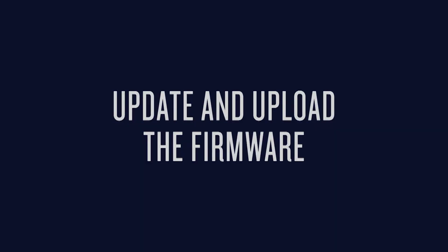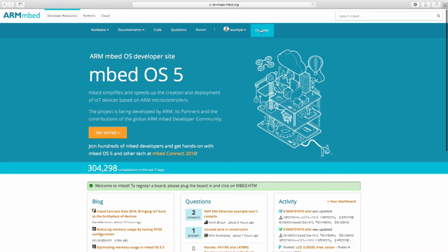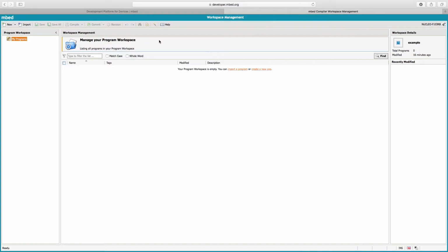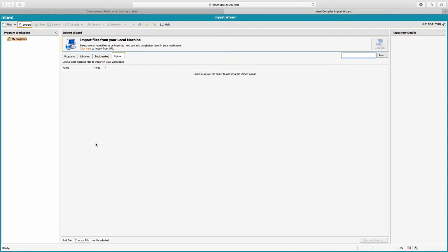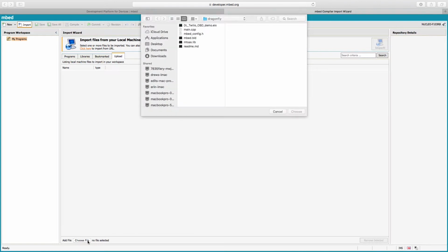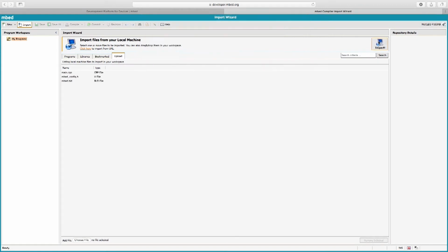The Dragonfly is an Mbed-supported hardware platform, which allows you to compile for it using the online Mbed IDE available at developer.mbed.org. After creating an account, open the compiler window from the menu bar at the top of the user home screen. Import the Mbed project into the compiler using the Import button at the left of the project page, or create a new project and import the individual files into that new project.